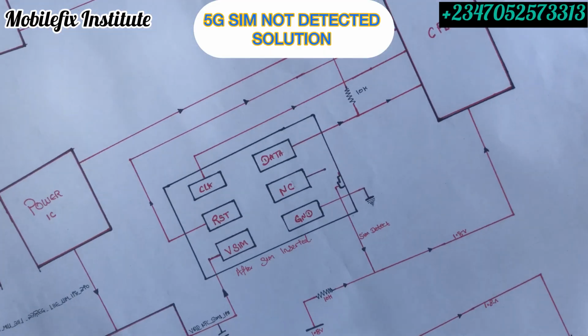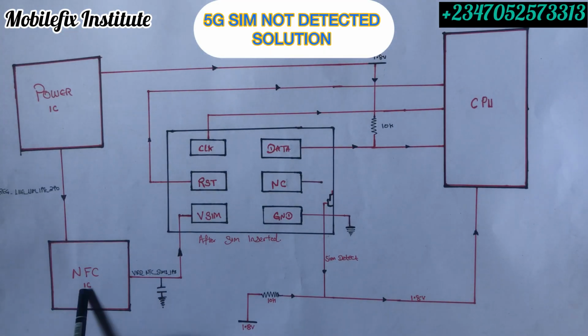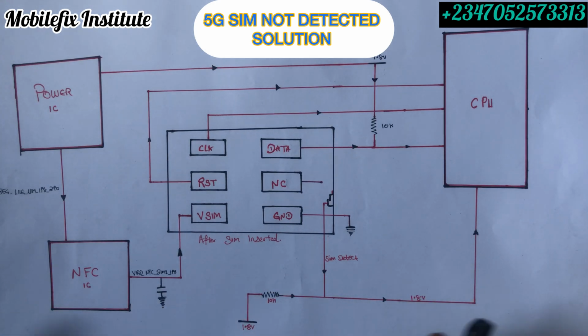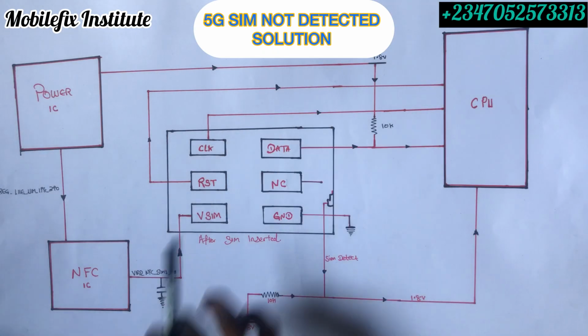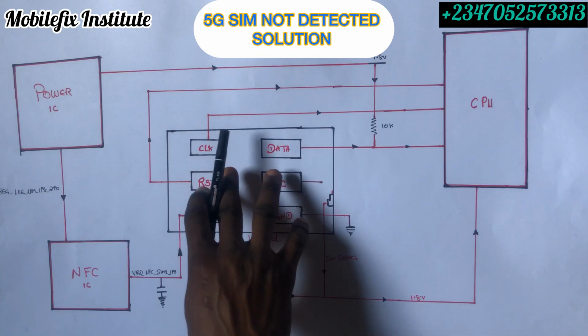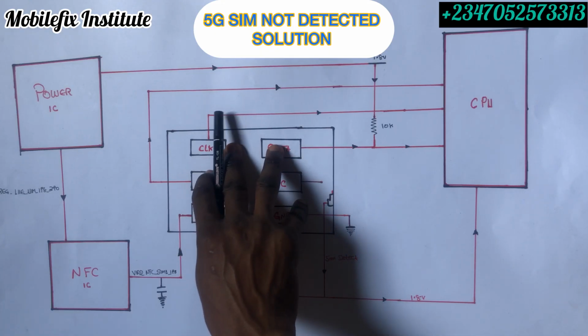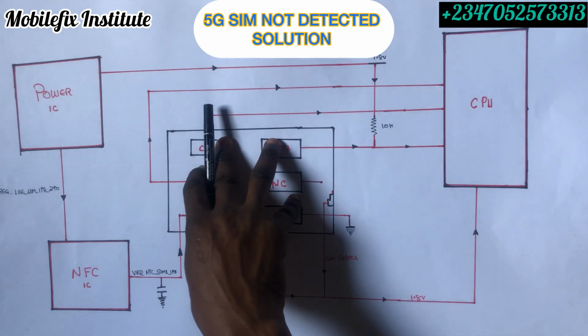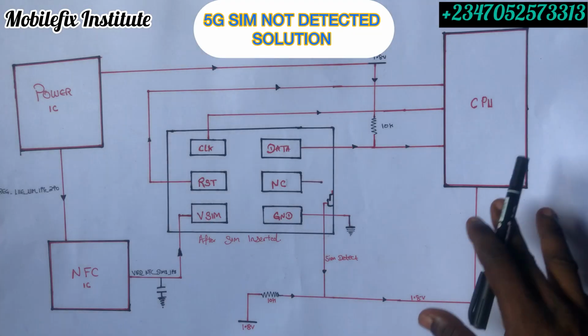So after this LDO has inputted this voltage onto our NFC IC, now NFC IC has different lines. It plays different functions, okay, with other circuits. So this output voltage, there are other output voltages, so you have to look for this VDD NFC SIM1. Okay, we also have SIM2. Now I'm explaining the SIM1 circuit here. The same logic applied to SIM1 is also applied to SIM2. So the same way you troubleshoot SIM1 is the same way you will troubleshoot your SIM2.